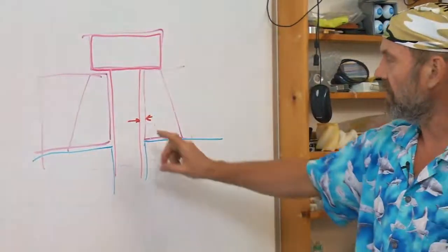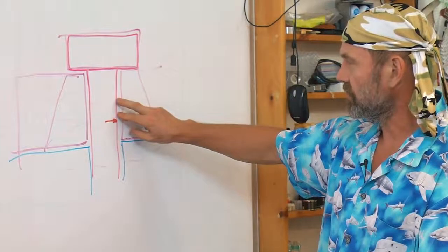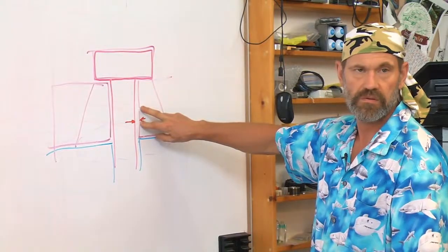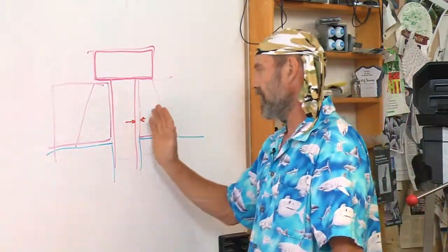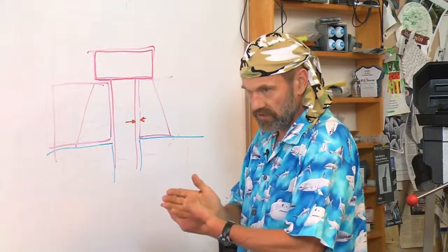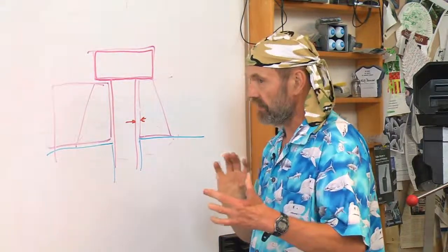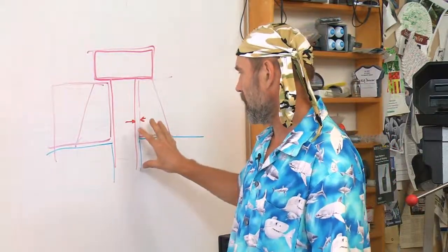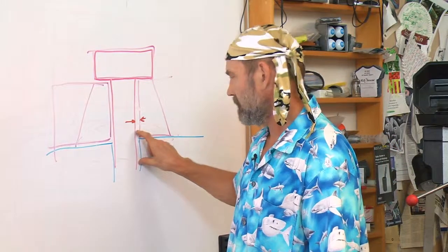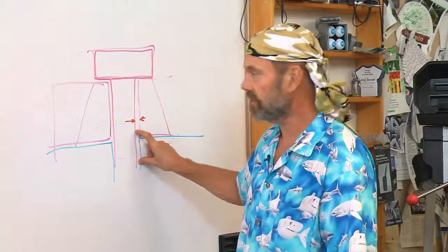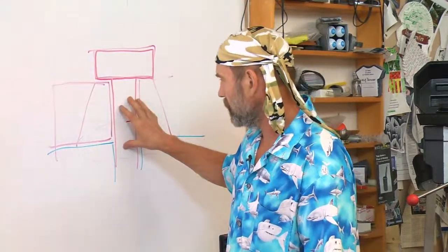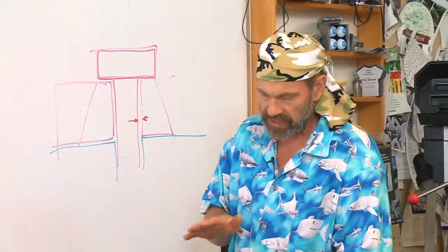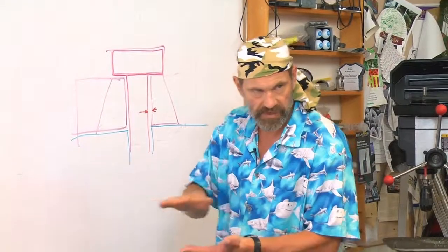You're not relying on clearance between the shaft of the bolt, or the shank, and the hole. You're not relying on there being zero clearance, and therefore it'll take a shear load. Because when you have a lot of bolts and a lot of holes, they can't all simultaneously engage the parts to have zero clearance. They only can all simultaneously clamp, and then together the summation of their clamping force with the coefficient of friction prevents the joint from shearing.